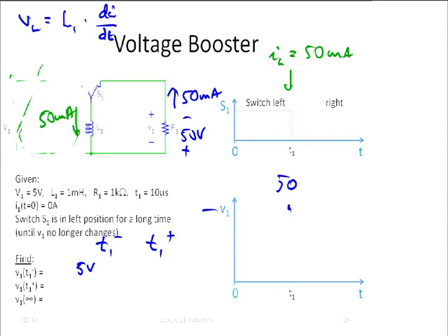And even if the source has only 5 volts, we can make 50 volts no problem using that inductor. Huh? It's quite interesting. So there ought to be some use for this. And then what's going to happen to the voltage across the inductor eventually? It's going to 0. Why? Because all the energy stored in the inductor is dissipated in the resistor R1. Consequently, the voltage is going to decrease exponentially. We can solve the differential equation, but it's even more interesting to understand what's happening here.